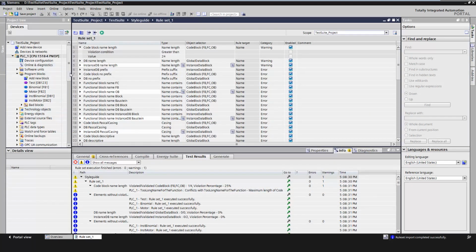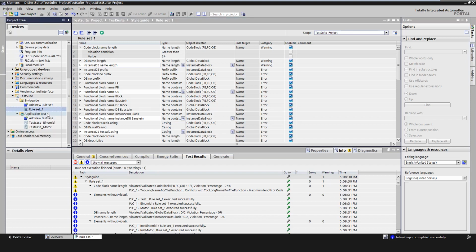We can create test cases to define functional tests for individual modules or an entire application. A test case contains definitions of variables and test steps. A test step typically consists of the value assignment to PLC variables, the values required for the test, the execution instruction such as the number of CPU cycles or time. It also contains the test conditions under which the actual values are compared with the expected values and a message is generated. When test cases are executed, the following steps are performed automatically.